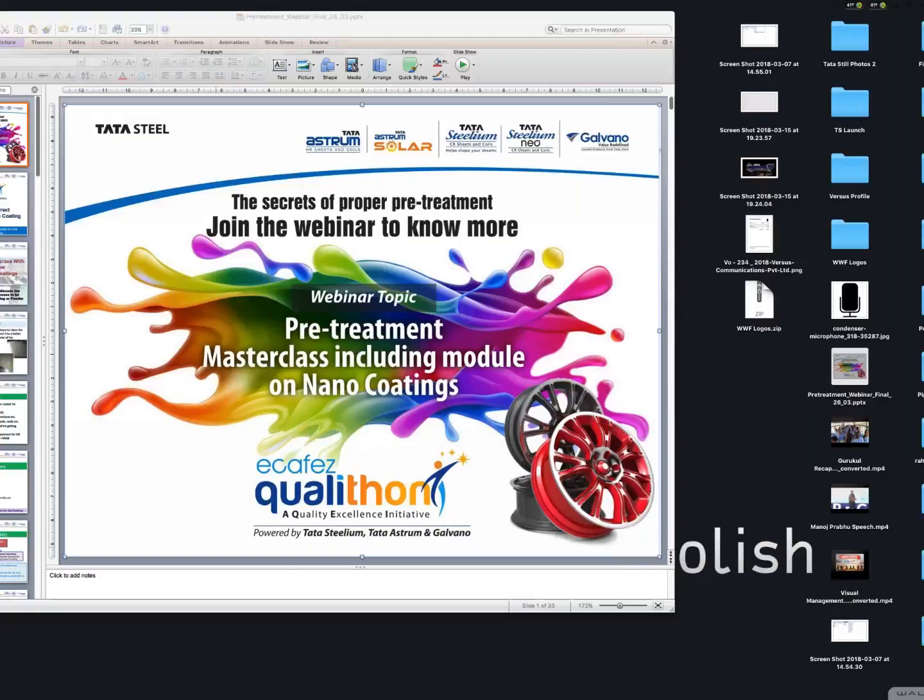Similarly in phosphating, if you keep it for more time, the phosphate layer will be thicker. Thicker in the sense, instead of 2 to 5 microns, it could be 8, 10, 12 microns. And there are chances of delamination because this phosphate layer is crystals on each other. So excessive coating of phosphate will be more brittle, and adhesion could be a problem. So better stick to whatever your chemical supplier has asked you.